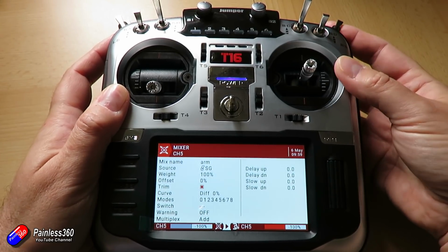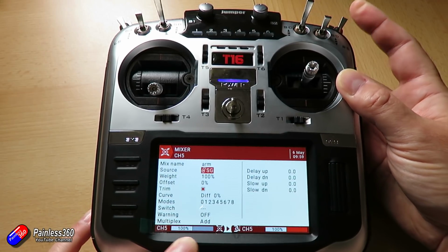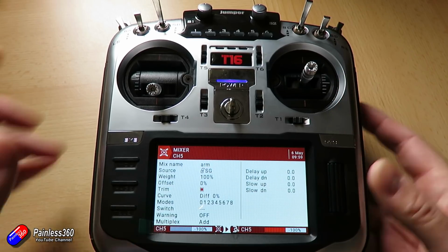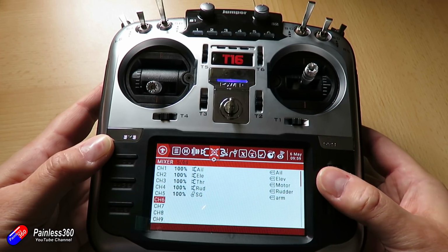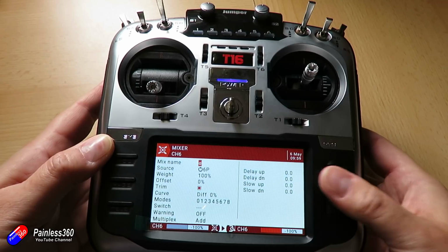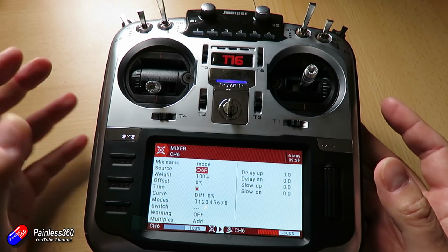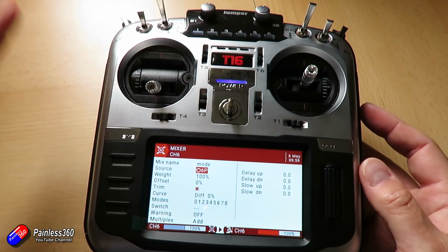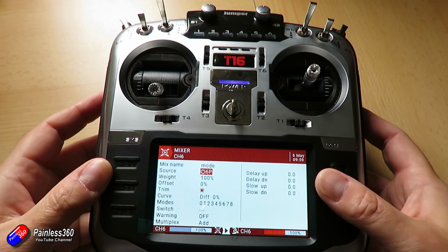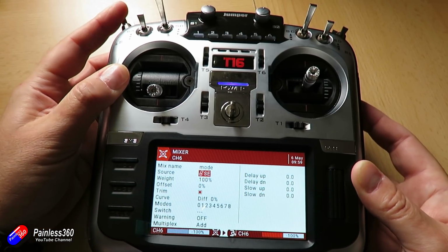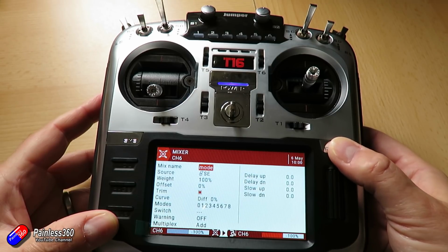There we go. And you can actually see at the bottom the individual channels moving, so both the input and also the output channel that it's connected to. So hit the roller button again, press exit, and then if we wanted this one to be mode, and again return, come down here. By default it's picking up the 6 positions. These are great for things like ArduPilot and ArduPlane, ArduCopter, but for now I'll just select, hit enter, flick the 3 position switch that I would normally use, and then come out of that, and there we are.